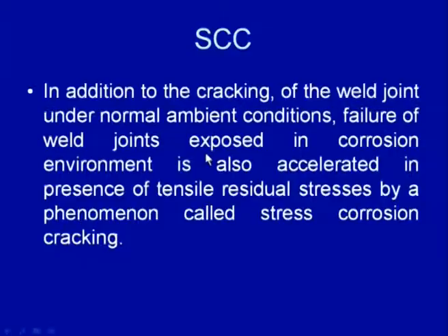So, in order to avoid stress corrosion cracking, first the tensile residual stresses are reduced using suitable treatment of the weld joint, and further the weld joint is isolated from the environment which is corrosive, or to which the weld joint is sensitive. So, the corrosion is prevented and the residual stress magnitude is reduced in order to avoid the stress corrosion cracking tendency.